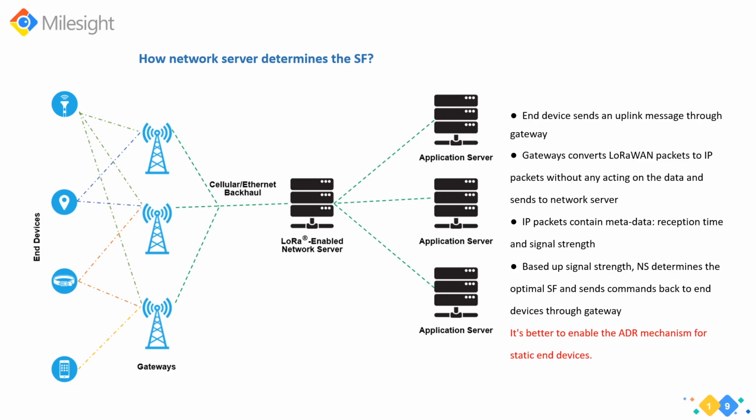If your sensors and gateway are deployed in a place for a long time, in a static state, not in a moving state, okay, the sensors are not installed in cars or on trains that are always moving, then in that case, you can enable this ADR mechanism.